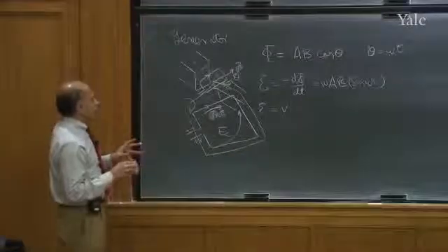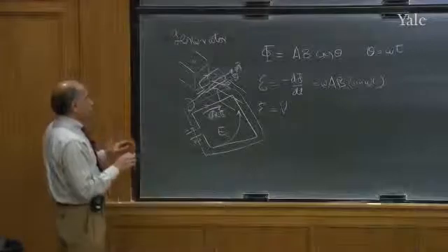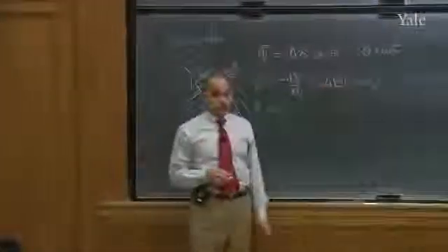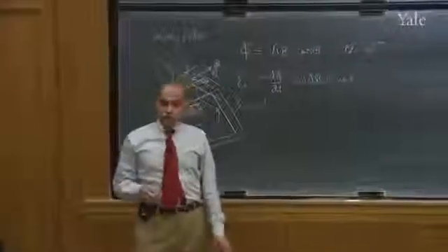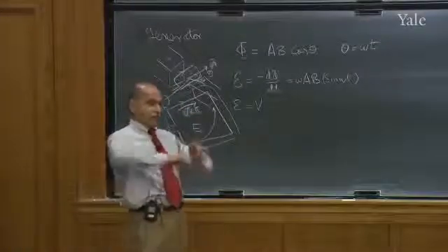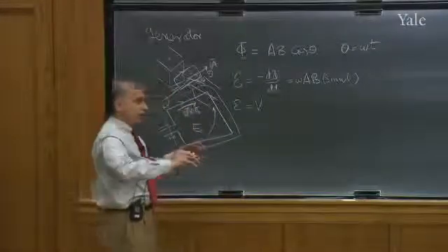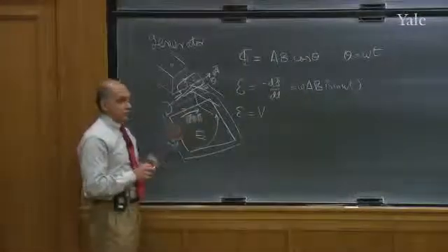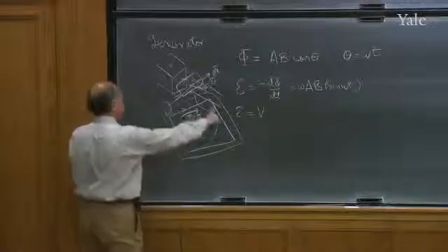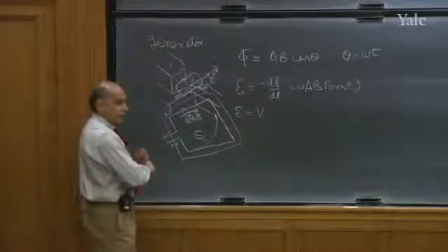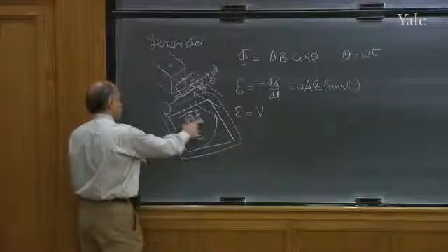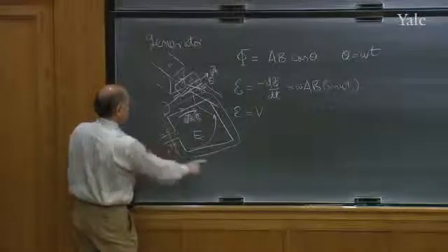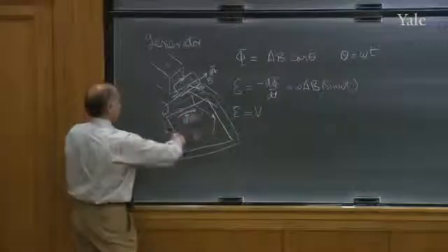So I'm giving you an option. If you don't want to look under the hood, you simply say, whenever you rotate a coil, you get that EMF. That EMF is like a voltage. Case closed. But if you really want to know what's happening inside the wire that made up that coil, inside the wire, the net force on charges is actually 0, or an infinitesimal amount left to make them move this way. That's because the V cross B force is countered by an internal electrostatic force due to pileup of charges that opposes it, so that inside it's free.